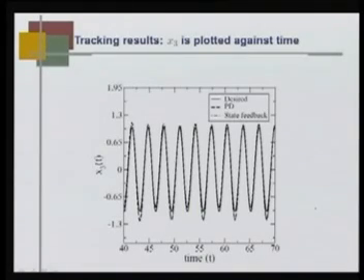Given that, the tracking result is x3 plotted against time, desired, PD and state feedback. PD and state feedback give the same result here for the tracking. You see the tracking is not as proper because the rule base that we have taken is very small, and also in the state feedback controller we have rejected the input of x1 and x3, the state feedback of x1 and x2.